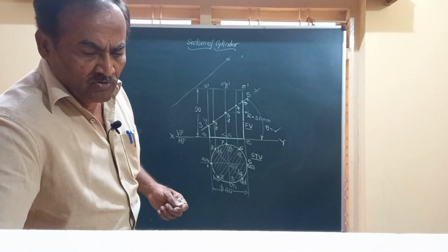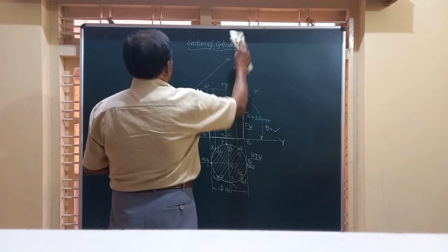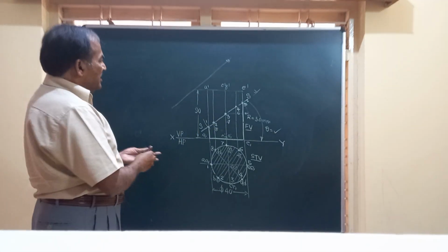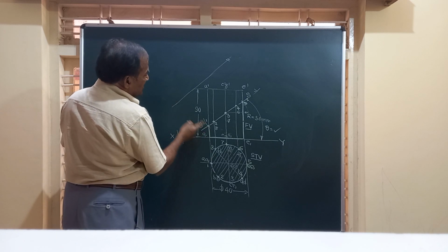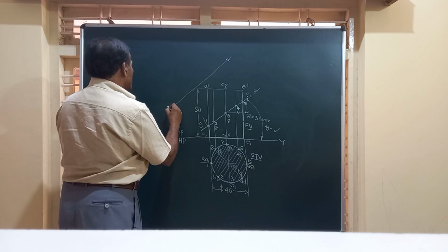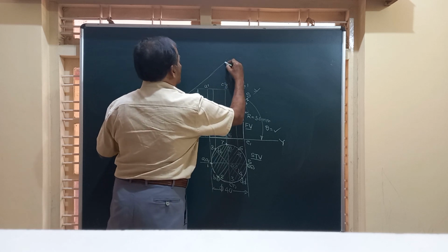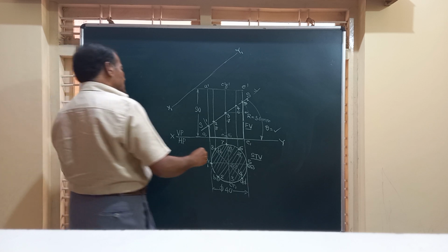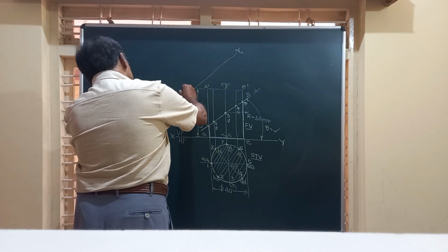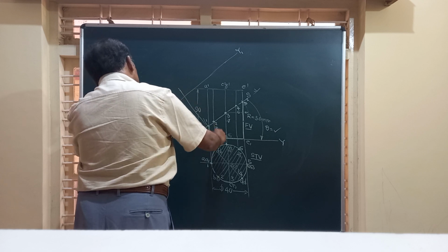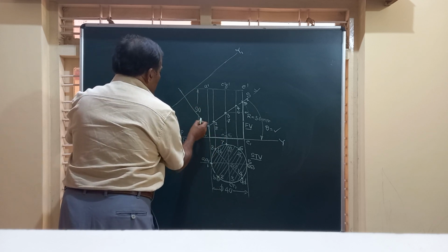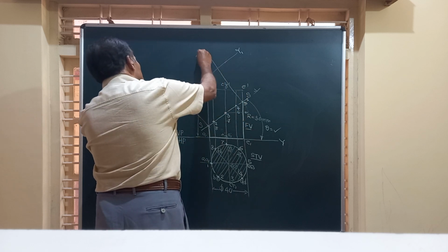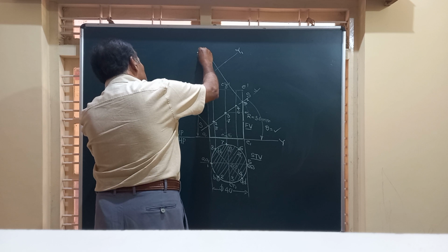Friends, now from all these points 1, 2, 3, 4, etc., let us draw lines perpendicular to SS, or perpendicular to this line, say X1Y1, some reference line parallel to this. So friends, I will mark them here. From 1, I will draw a line perpendicular to that, a line like this. A line through the last. Then lines through all of these you should draw.